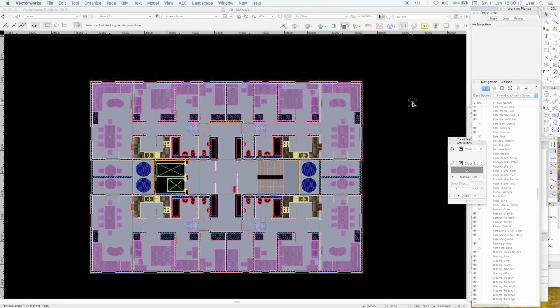It's enormously time-saving. The hassle of trying to change the attributes of an object that are not set by class: they show up in the viewport, the line's too heavy, it's the wrong colour, you've got to go back into your drawing and find it and change it, and it becomes a boring process of trial and error to control the graphic qualities of those attributes. And so that is the way to do it. Be very disciplined and set your object's attributes by class.